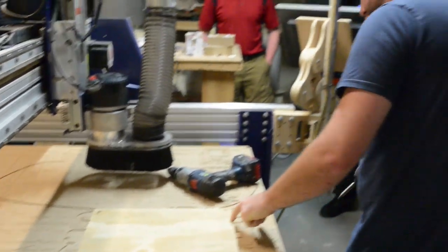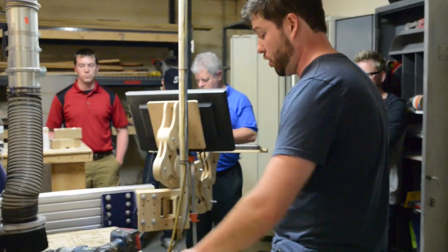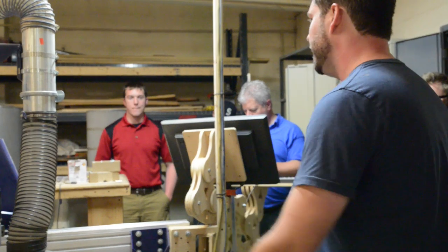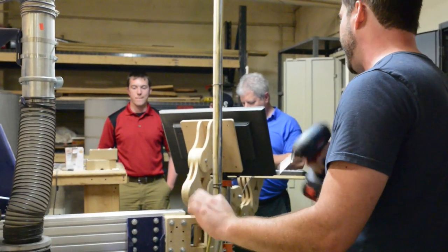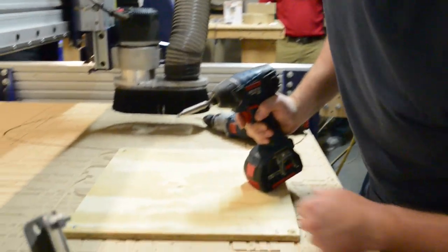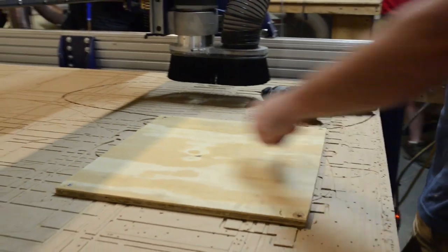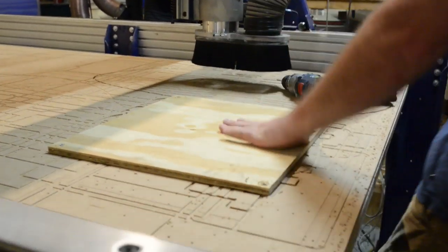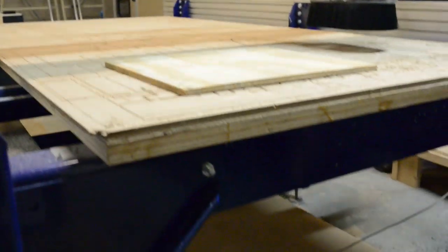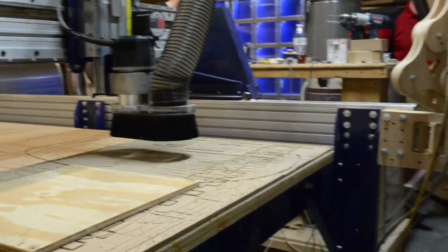Very important to make sure you fully suck down the piece of wood to the spoil board. Sometimes when you do that, even if you see the screw head touch the top of the wood, it still might be above it. So you've got to make sure, visually inspect all the way around that you are actually touching the spoil board everywhere. And if I had a really big warped piece of wood, maybe I might have to put more screws down. But for our purposes, I'm okay with that. Okay, get these out of the way. So our piece of wood is now adhered to the table.